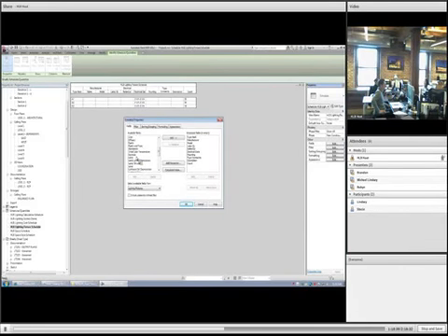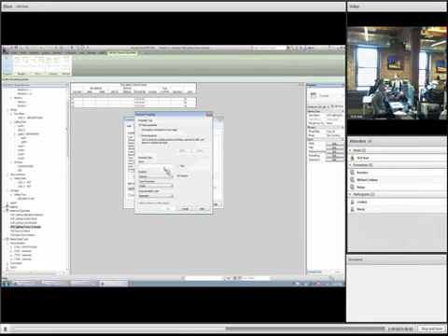And for your schedule, it's just like in Excel when you are picking and choosing. I believe there's a similar interface for data input, but you can add columns. The scheduled fields in this particular schedule are type mark, manufacturer, model, those types of things. So quickly, we can add a parameter. Let's call this ballast code.